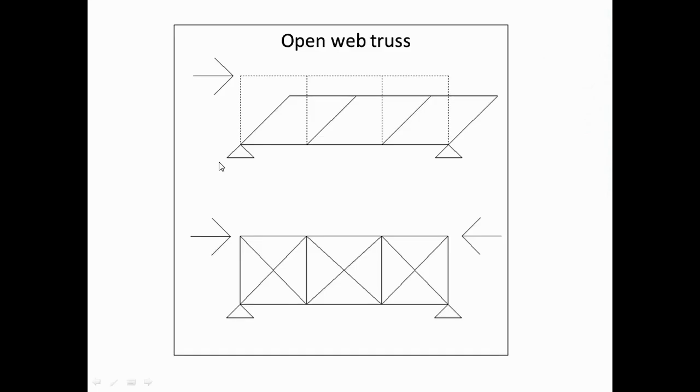There always will be. So what I mentioned earlier was the idea of the truss, which is now a series of independent lattice, if you like, a lattice work. This can be steel or timber or concrete. Again, doesn't matter. The principle is the same. Here's the flange at the top and the flange at the bottom, linked together with a series of uprights. Now, the reason for the triangulation here, the cross bracing, is because, again, you remember early on, if there's any kind of lateral load on the structure, it's going to fail, isn't it, in that direction? It's going to shear away. So this triangulation is going to prevent that happening.